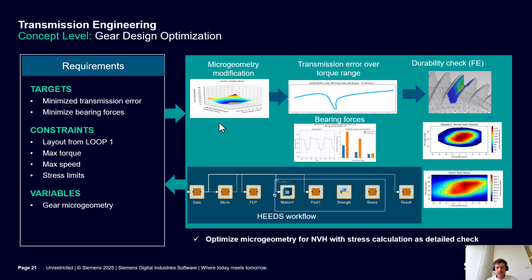And so, of course, here the goal is to optimize the gear geometry for best NVH performance, but at the same time making sure you also meet, for example, criteria on root stress, on contact stresses, flash temperatures, so more the strength and durability and efficiency type of KPIs.